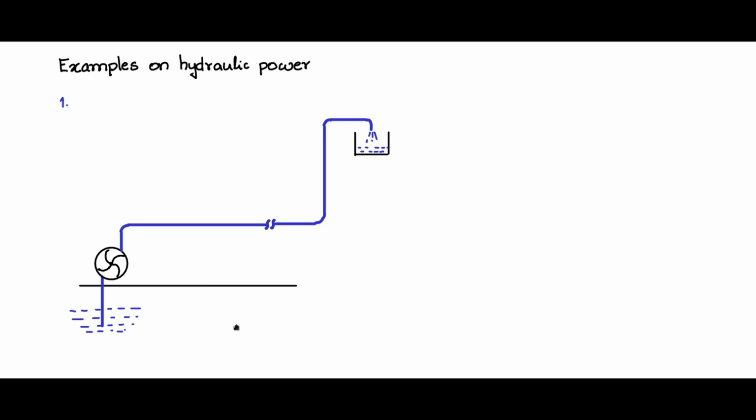Now, what is the suction head? Suction head is from the tip of the suction pipe to the center of the axis of the pump. So let us mark that, and I will mark that one as HS. This is the suction head. What is the delivery head? From the center of the pump axis up to the highest point that the water reaches up from the horizontal would be the delivery head, HD. Okay, that is not all.